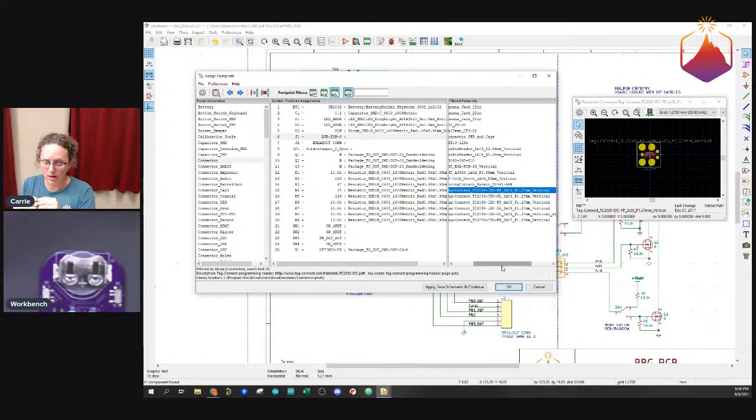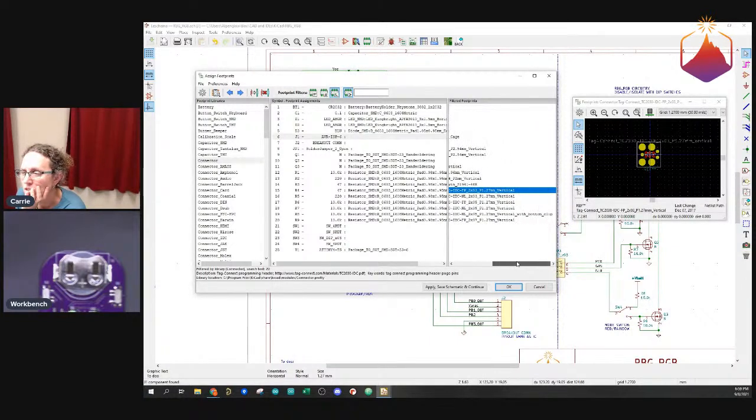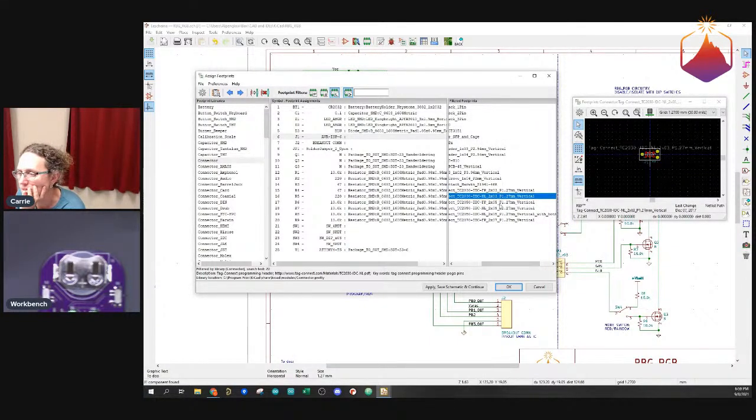They're smaller than the normal connector, and you can just press them down to the board, click program, and have it program your board, then take it off and go to the next one. So you don't have the wear and tear or the cost of putting an actual connector on your board. You just need pads that the spring contacts come into contact with. So it's sort of similar, but not really what we need.